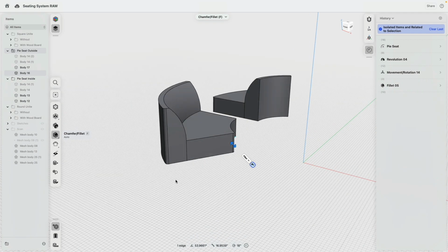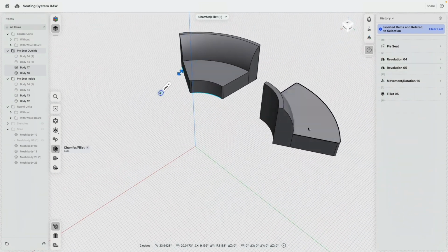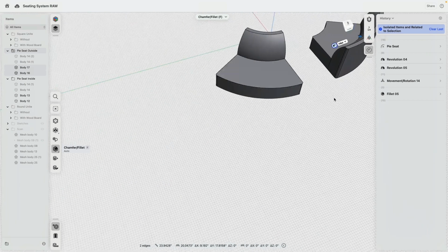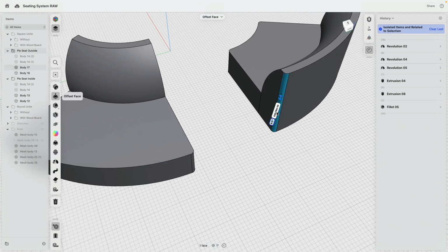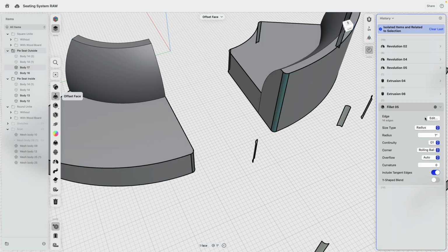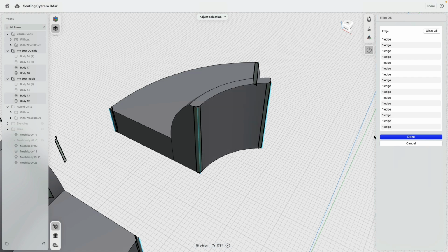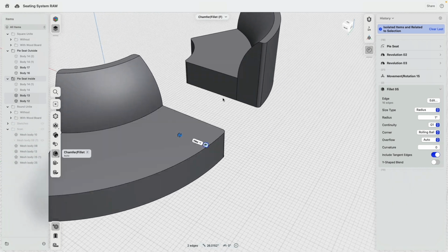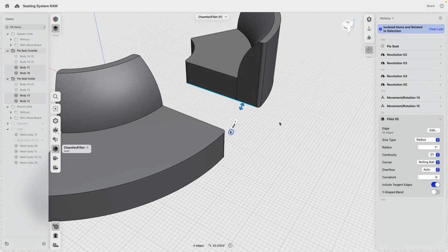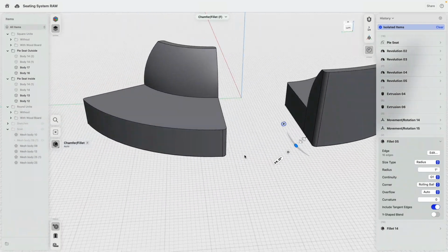The bottom we can select here. Oh, I didn't round actually these edges. Okay, so that means if I go to this and say this is fillet 05, there we are, and edit. Just add these edges, please. Thank you. Good. Click, click, and click, click. 0.25. Round this a little bit.